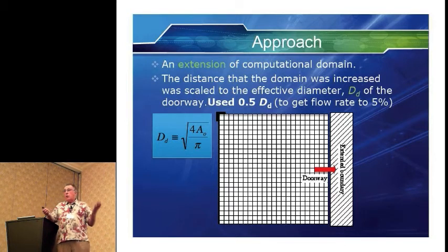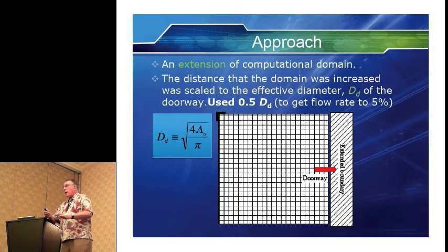Let me show you the results that they got. Now, we didn't only look at mass flow rate. We looked at, is it getting the neutral plane right? Those are parameters that are not so arbitrary. The other two are a little bit: the average lower layer temperature, and the smoke layer height.